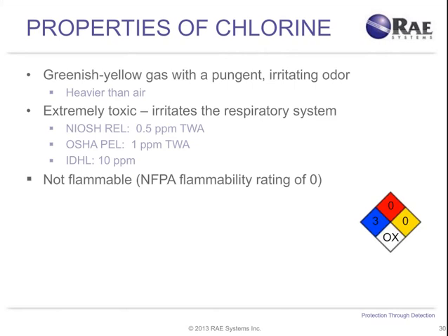It's extremely toxic, like I've already said. It irritates the respiratory system and the eyes, and when it gets into the lungs, it unfortunately reacts with water to form hydrochloric acid, and that acid prevents people from being able to breathe. So we have 1 part per million TWA, an exposure over an 8-hour period, according to the OSHA permissible exposure limit. And look at the IDLH, the concentration that's immediately dangerous to life and health. That's only 10 ppm. At that concentration, it's already dangerous to life. Chlorine is not flammable.